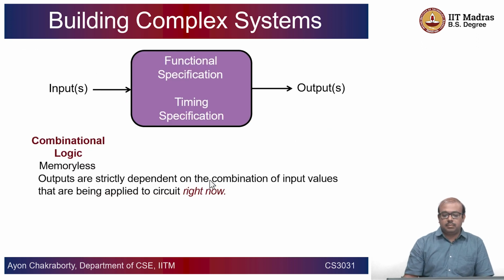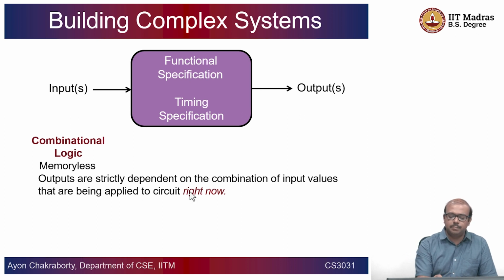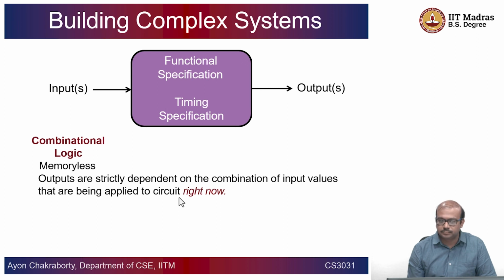Okay, so combinational logic. So we are going to look into two kinds of logical elements or logical element design. The first one is called combinational logic. We call this a memoryless design. So the outputs are strictly dependent on the combination of the input values that are being applied to the circuit at that point in time.